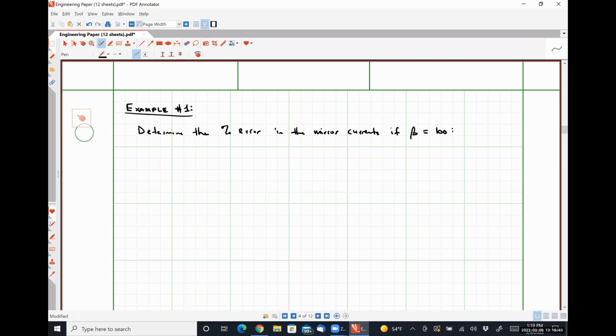Okay. And our circuit of interest is this guy here. Here we have IREF. And then our sense transistor is going to have effectively a total area of twice AE. So this is a shorthand for saying there are two reference transistors in parallel.